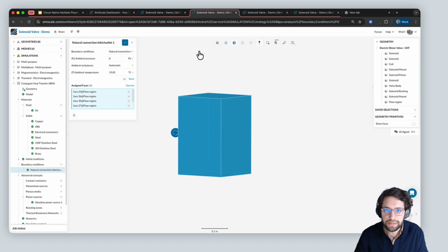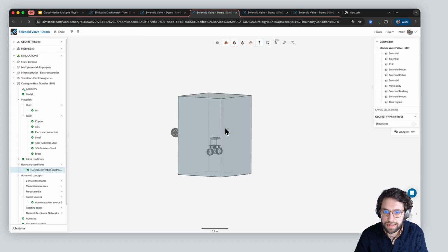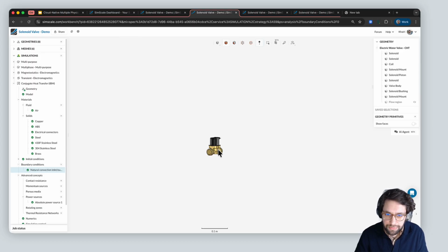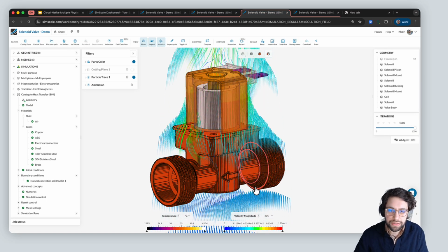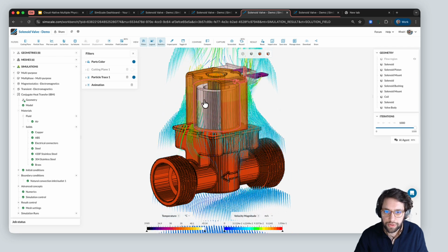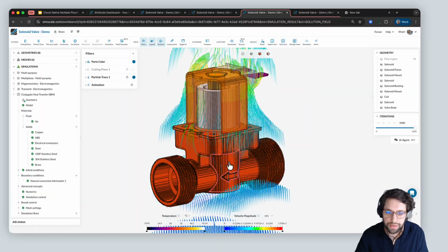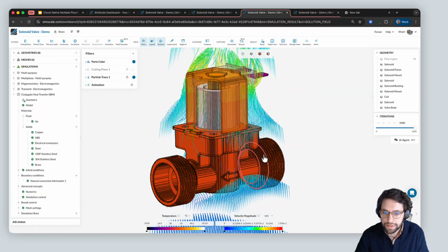And in this case, it is our coil mainly, and we can from this also analyze how much heating overall is happening in the system. So we see, for example, that the coil reaches a temperature of around 45 Celsius degrees, while the aluminum housing of the solenoid valve is still within acceptable temperature, around 30-35 Celsius degrees.